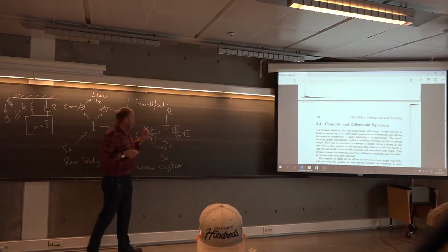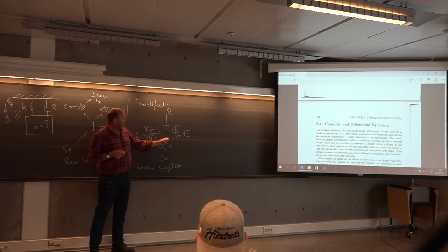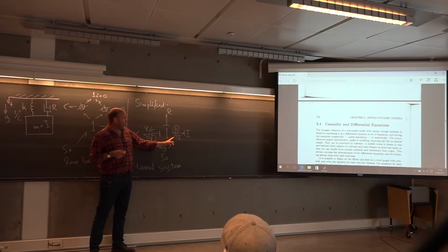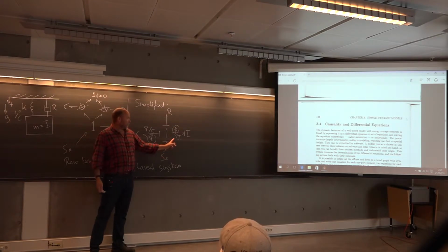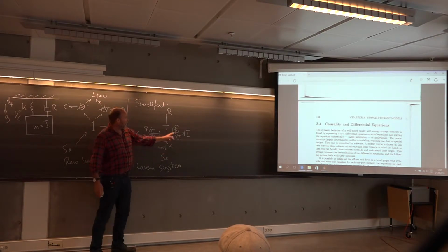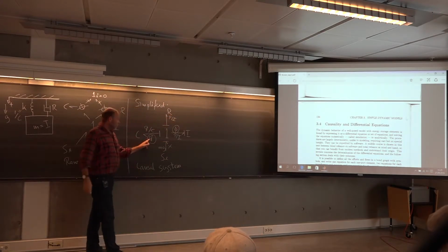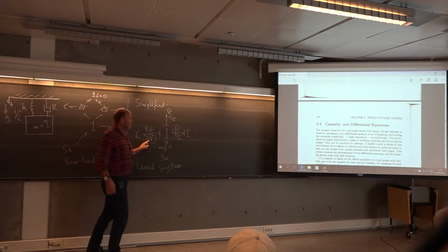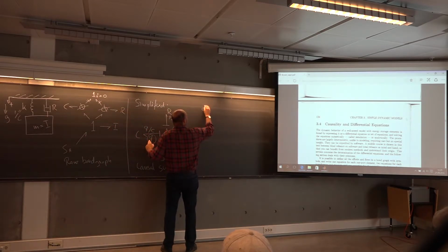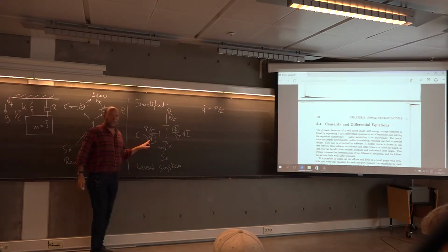Furthermore, we have now found the flow responsible for this one junction. It is where we are missing a stroke, hence it's going to be P over I. This is the flow. So down here I've just set an x. I could have set P over I here if I wanted to, but normally we don't care about it. But here also I have the flow, P divided by I. And also here. But now this position is taken. It's already a q dot there. But then they have to be equal. So q dot equals P over I. So that's my first differential equation.